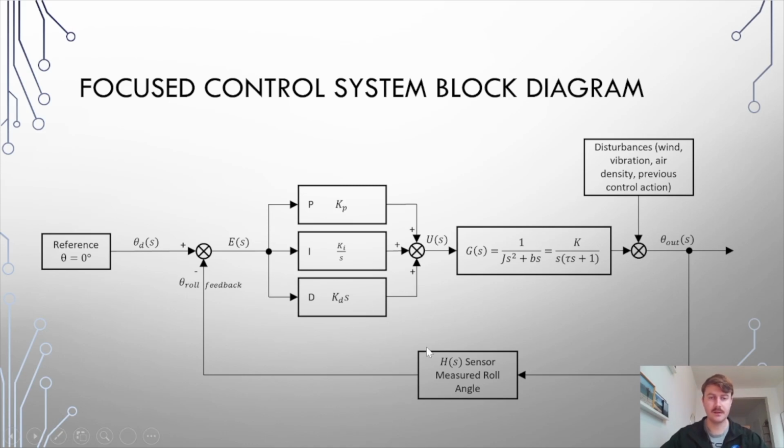And then the D gain only sends a signal to the change of error. So if the error is 0, that's fine. And if it starts to turn, it'll create a signal that initially opposes that turn. But once it's turning, it will keep turning, that's fine. So when the system starts to go out of its stable position, it will send a higher spike to try and keep it there, and then it'll leave the rest of the correction to the P and the I block.